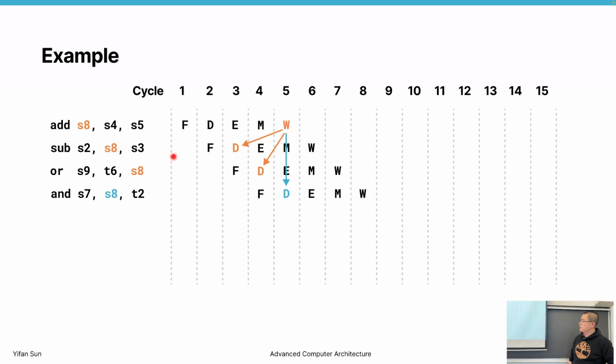If we force a pipeline execution, we actually need it in the 3rd cycle, right? We need to decode, and decode is also reading the register. If we read from this register, we'll read some garbage data. It's from the previous instructions, not the result we're expecting when we consider program order.